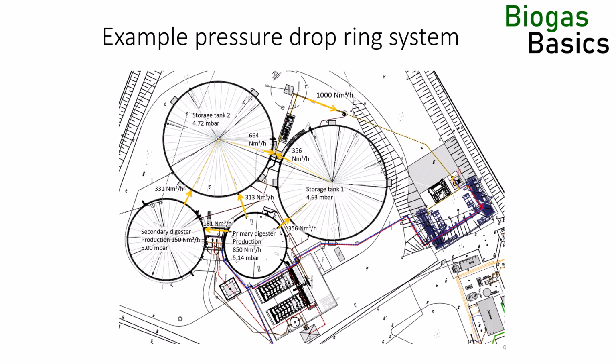First, I will show how the gas management algorithm works on a real plant. Then I will compare it with the calculated pressure profile using the pressure drop method for ring systems. The pressure gradient over the plant changes between charging and discharging, and the gas domes must be actively managed to make full use of the storage capacity.